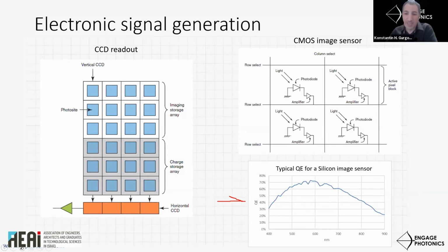In general, CCD image sensors are more expensive, they exhibit superior uniformity and noise characteristics, and they are mostly used for large format, high-end applications. In CMOS image sensors, each pixel contains a pre-amplification circuit with a few transistors. Image sensors enable electronic amplification of the signal, called analog gain.